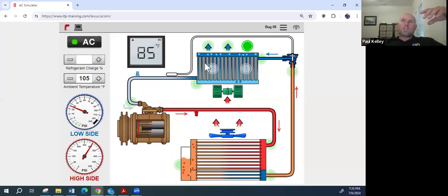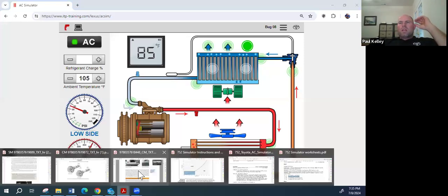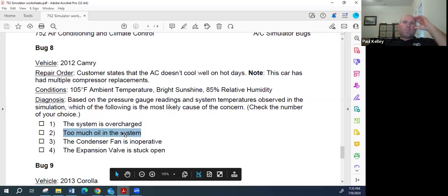We're getting the cooling because there is evaporation inside, and that's absorbing massive amounts of BTUs in latent heat form, not in sensible heat. So that oil's not evaporating. You've got refrigerant coming into this evaporator, cool, but it's way less refrigerant than it used to be, and now it's just a bunch of oil. And the oil just gets circulated. It doesn't change state. So you lose a lot of cooling. Make sense?